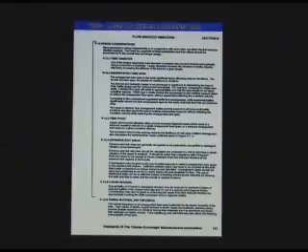What were the units on Q? BTU per hour. Pardon me, on the heat transfer rate itself, Q, BTU per hour. The U value would be BTU per hour per square foot per degree Fahrenheit.